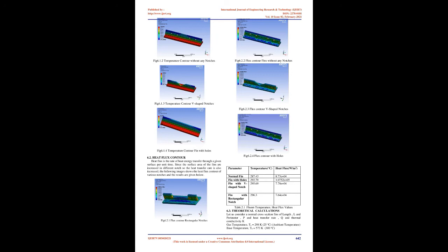required to obtain a solution. After the model is imported into the CFD domain, the next step is to mesh the domain. To get better results using the CFD tool, it is mandatory to use a better quality mesh, hence the meshing of the model is generated and the naming of the sections is given in the model for computing purposes.